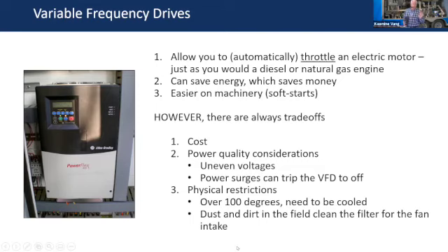One of the things I'm going to talk about right now is harmonics and harmonic distortion a little bit. I've got a few slides on it because PG&E and California are having a terrible time with this right now, and it's going to get worse with all the solar energy being produced in the state. With all the VFDs, you've got changes in the power being used at different locations constantly, and it makes uneven voltages and other issues happen. Those harmonics can occur and can trip the VFD or cause damage to your pumping system. So there are all these things to deal with too, and I'll talk about that later.